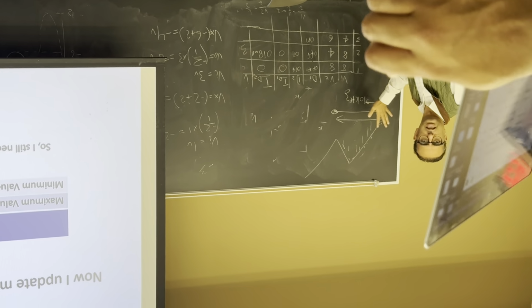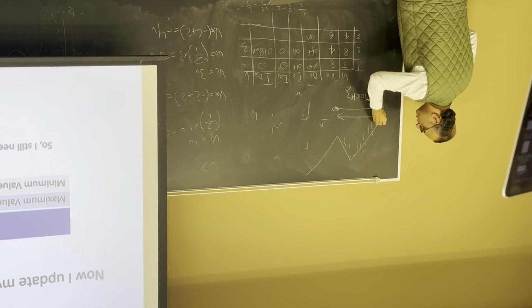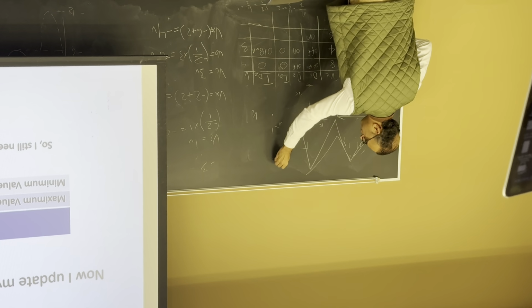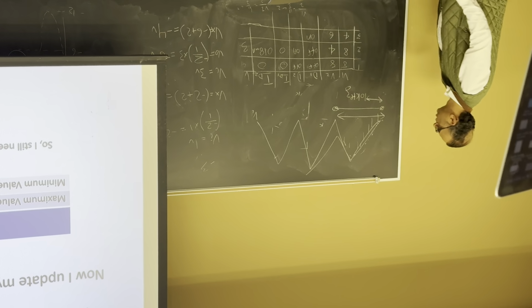But we could do it every 5th cycle. Perfect, but then you're reducing the control bandwidth. You're investing in things and now you're not using it. So what they do is, imagine if it's high frequency enough, they assume that this curve is constant.